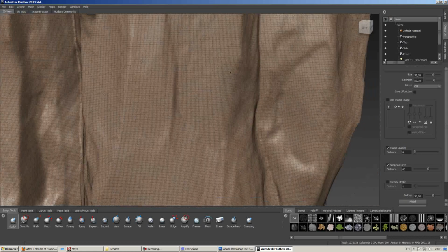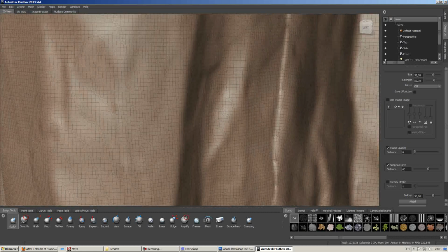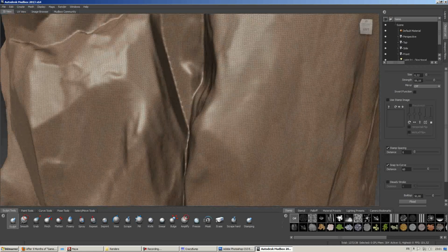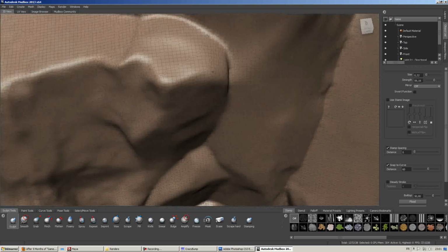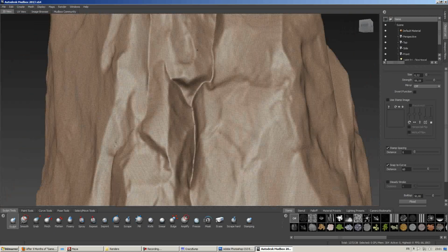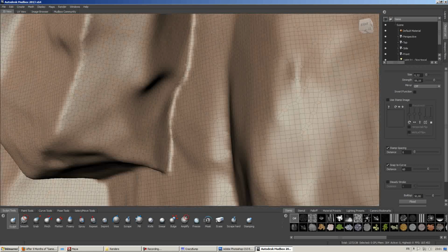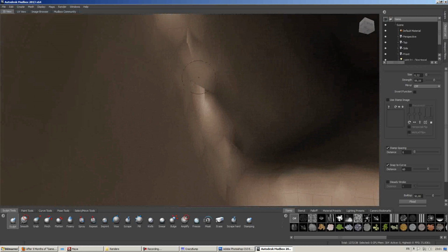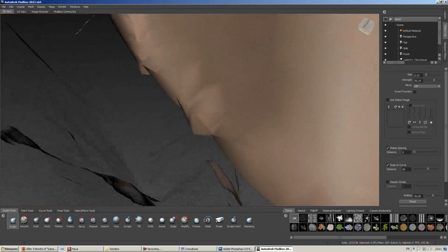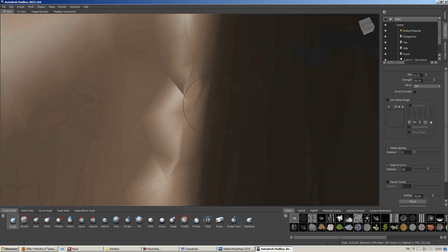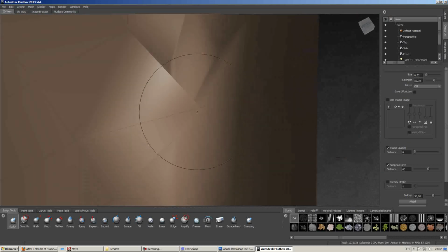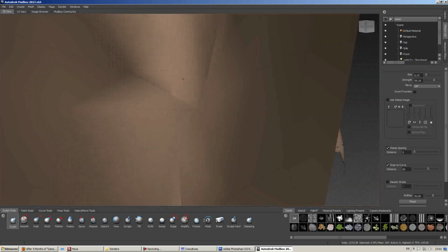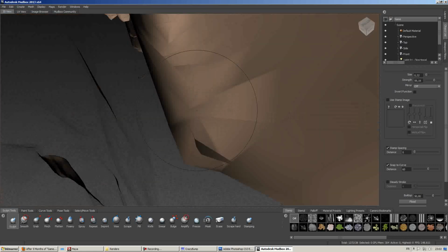Now, once you zoom in, you'll see that it is actually quads, but sometimes some of these areas, for example, a non-manifold geometry, let me find one for you. Usually they'll appear around the edges, in the cracks. Could be difficult to find sometimes, and here is a good example of non-manifold geometry. You got T-shaped faces, which means that there's one edge and you got three faces coming out of it, which won't work if you try to subdivide this.